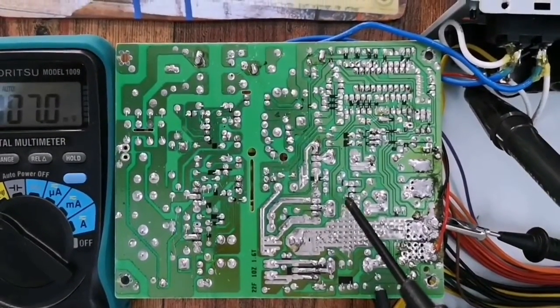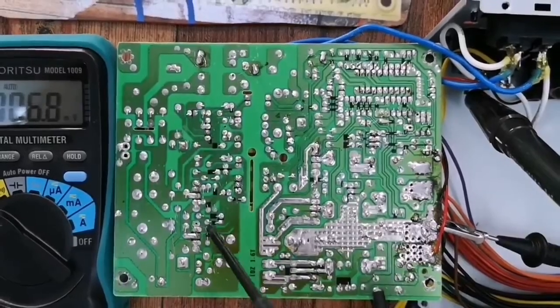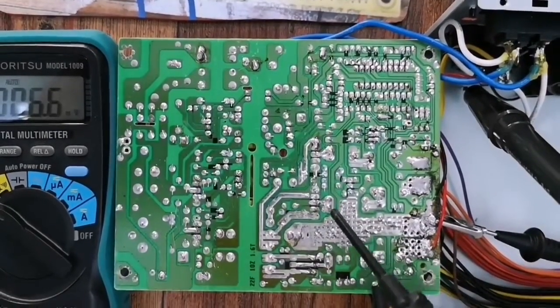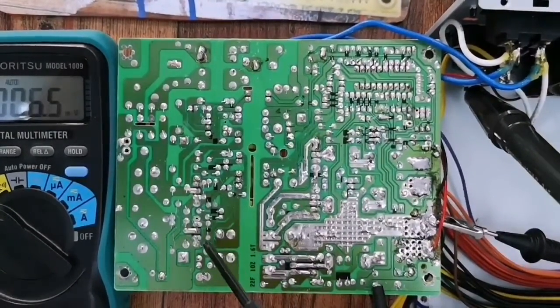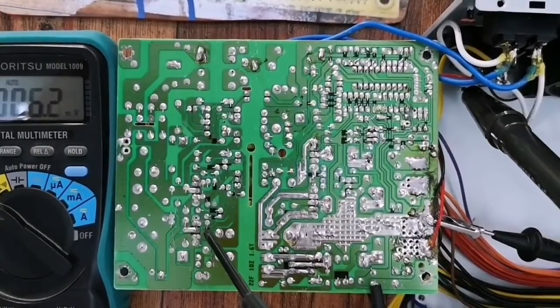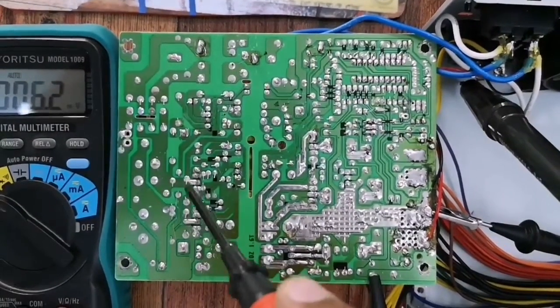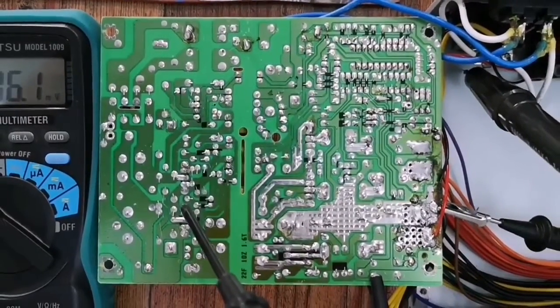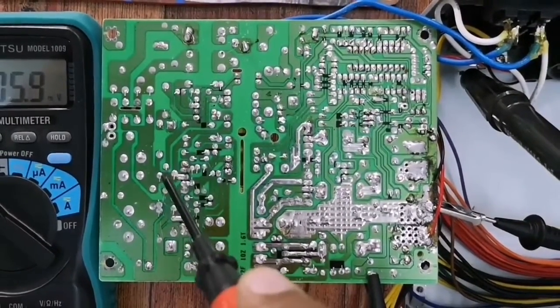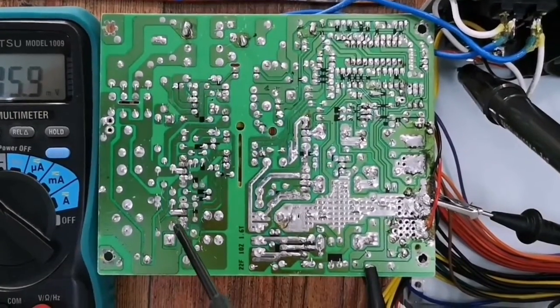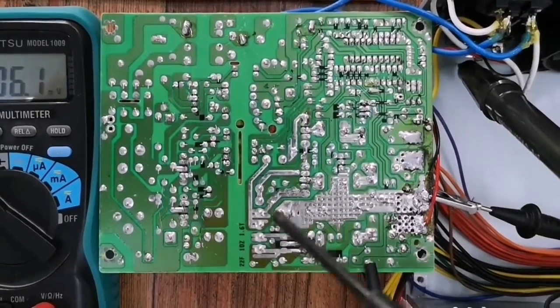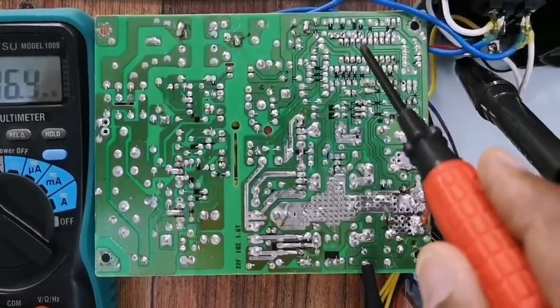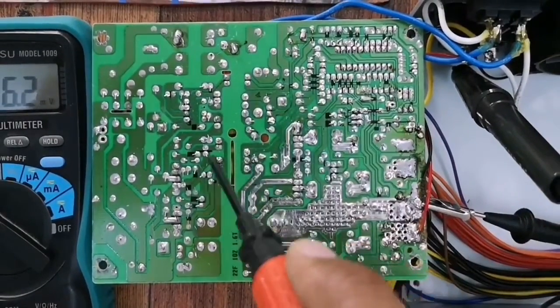The second reason, again, to get any current at the secondary side, the main switching transistors need to activate at least, even with an oscillating or on and off signal. But as we checked before, no signal is reaching there at all. So my conclusion, the signal output from this IC is not reaching the main transformer.